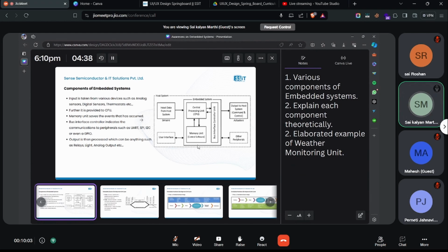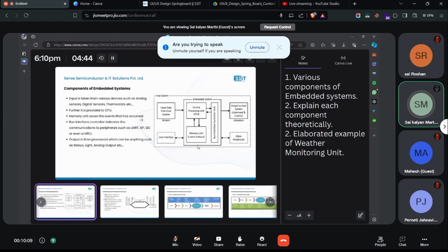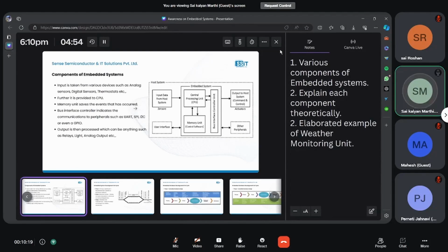components of weather parameters that need to be monitored. At the BTech level, you guys could have come across a weather monitoring project which everyone has done. Basically, you take a temperature sensor, I mean a DHT11 sensor, which probably everyone has taken. It will give moisture and temperature, and you can take a raindrop sensor to detect rain, but it will not work in the real world. So we will have industrial grade or industrial standard sensors which we need to consider while developing a system.